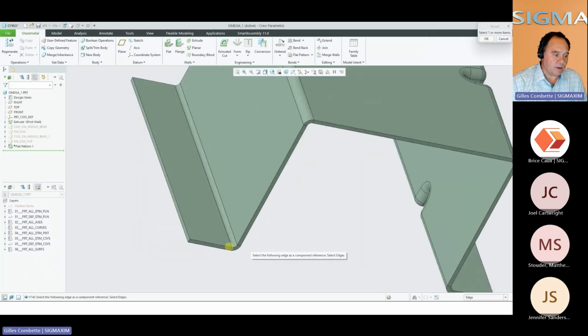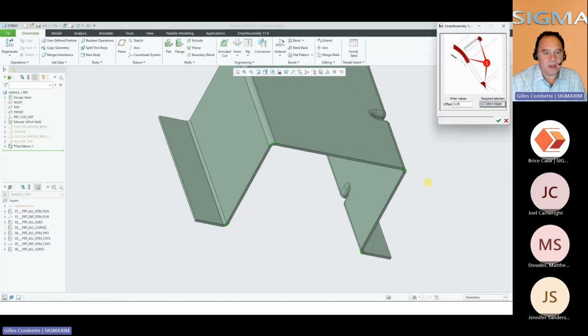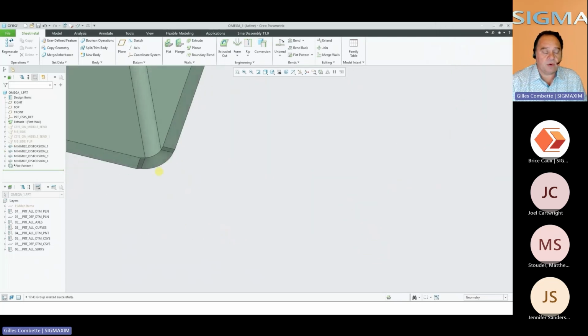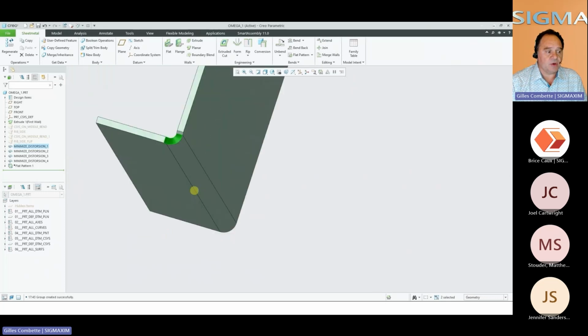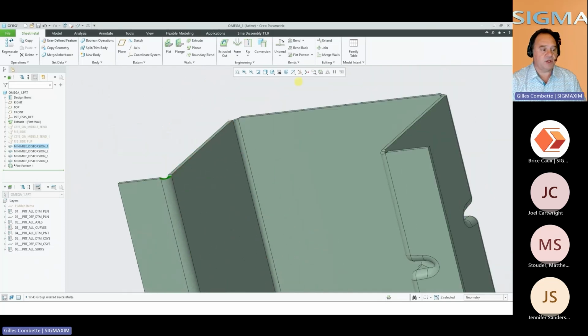This little deformation might be okay. So in those areas here, specifically where we're clicking, in those round areas, those little deformations might be fully acceptable. Most of the time it is fully acceptable. Sometimes it's not acceptable for some specific design reasons. And because it's not acceptable here, we have decided to add those kind of new features to control the deformation.